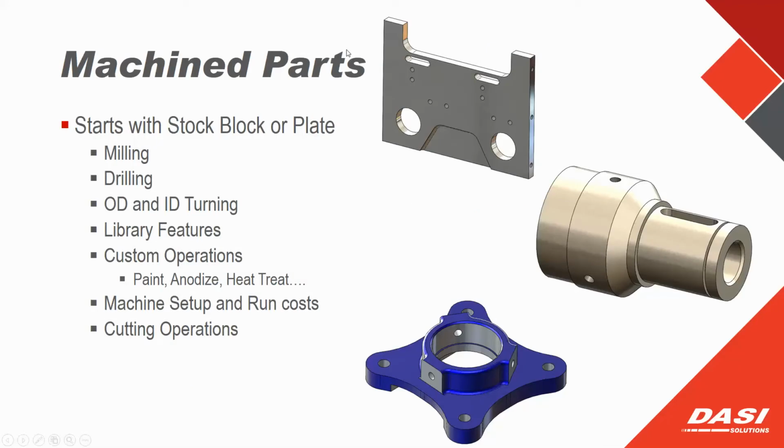So first I want to go ahead and show you a little bit about machined parts. Now, machined parts, again, are going to start off with either plate or block stock. So if the thickness happens to match the plate, it could just very well be a profile cut and then some milled and drilled operations and maybe a second setup like you see with the top part here where there's actually some tapped holes going in from the side. What you can also do are turned operations on the lathe. These are going to be OD and ID drilling, but they will also throw milling operations, as you'll see here for the slot that we have up there on the top.